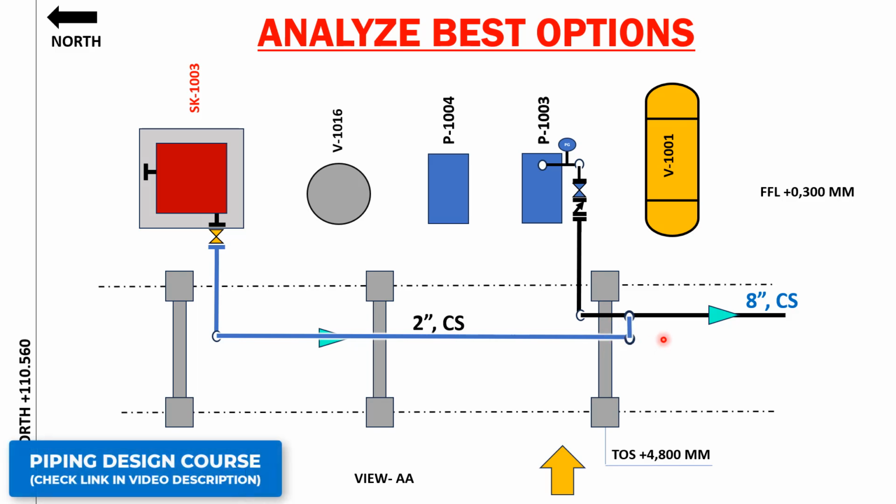I'm moving the line a little bit over here. That distance you can keep with respect to your pipe spacing calculations. Generally we need to have nearly 3 to 4 inch gap between pipe to pipe, but this calculation needs to be done. Conceptually I'm saying this. Here I'm just putting it logically, but in actual design we do a calculation, we check there is enough space, and only then we provide it, because you need to provide support guides and everything. For that you need to have space, but you have to understand the design first of all.